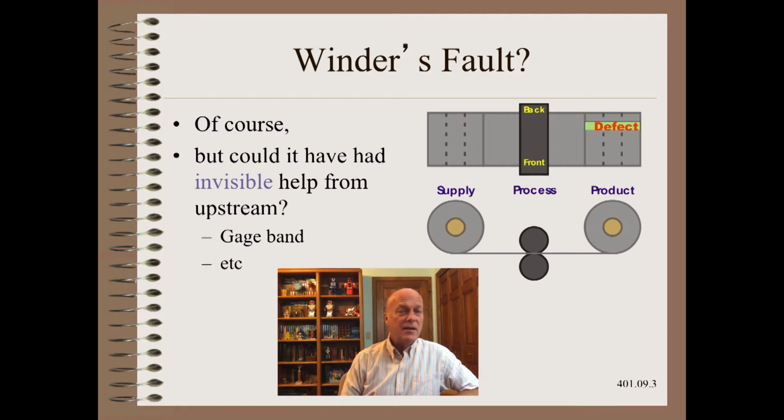Excessive tends to be in the 1 to 10% range. 1% web profile thickness variation is usually no problem, and 10% is usually no saleable product.